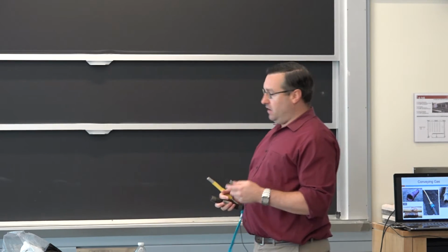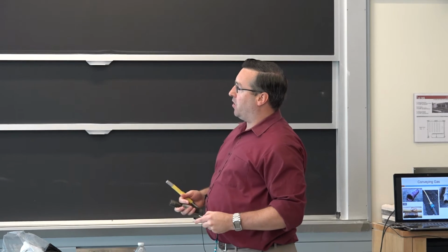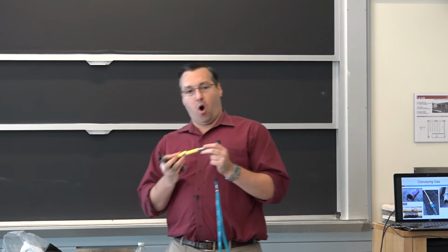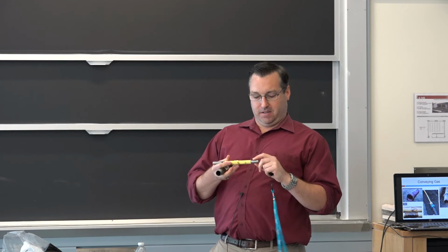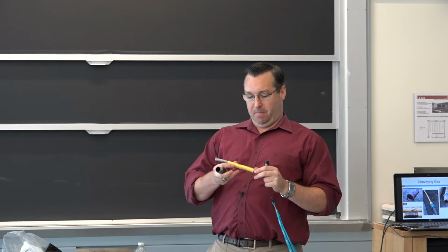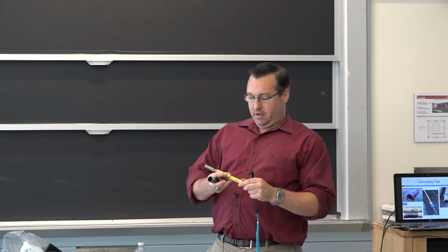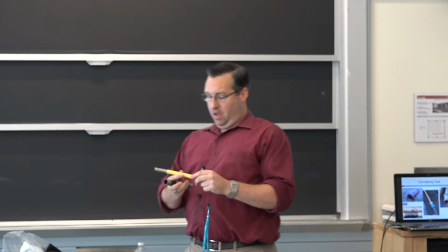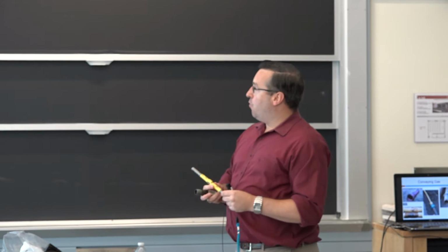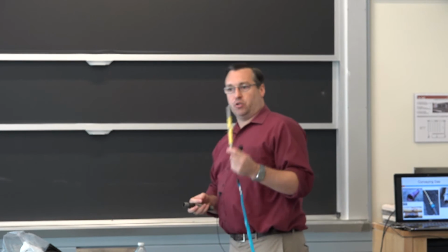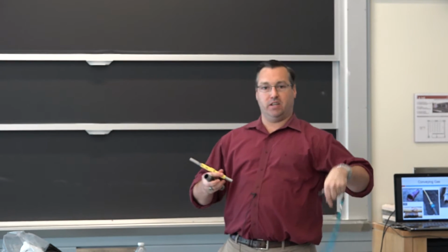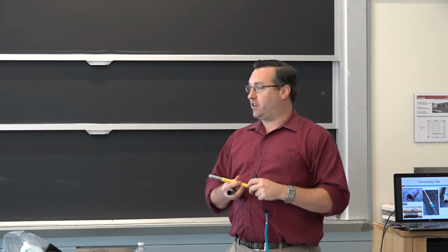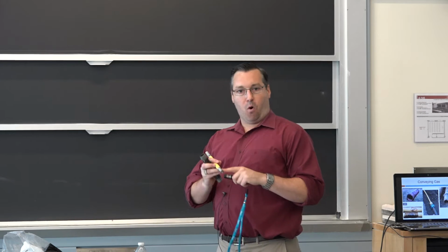And the reason why some of these houses were burning down was because when they manufactured this material, the wall thickness of this material, and this is the sheath around it, the insulating properties of the sheath and the wall thickness, when some houses were getting struck by lightning or lightning was hitting the ground, the energy was enough to actually puncture the wall.